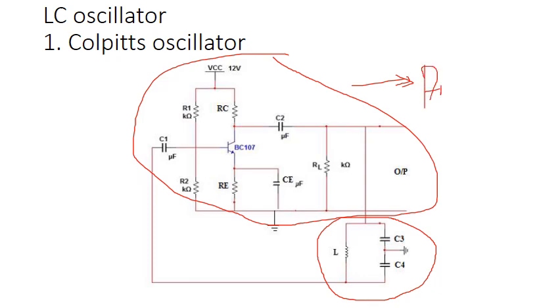So this is the amplifier stage and this is the feedback stage. It is named after the scientist who invented this oscillator, Colpitts. This type of oscillator uses an LC circuit in the feedback loop to provide the necessary phase shift, and it acts as a resonant filter that passes the desired frequency of oscillation.